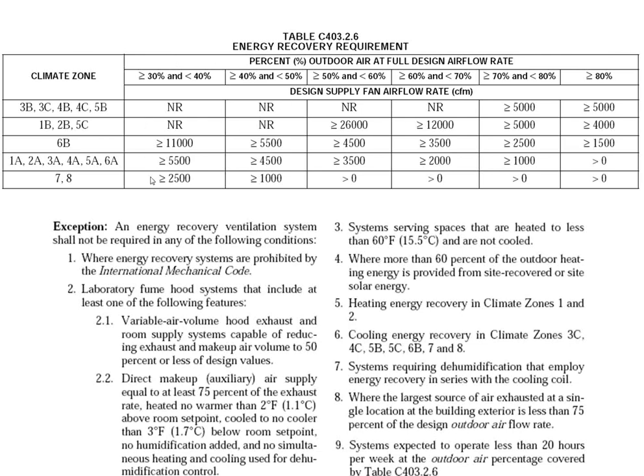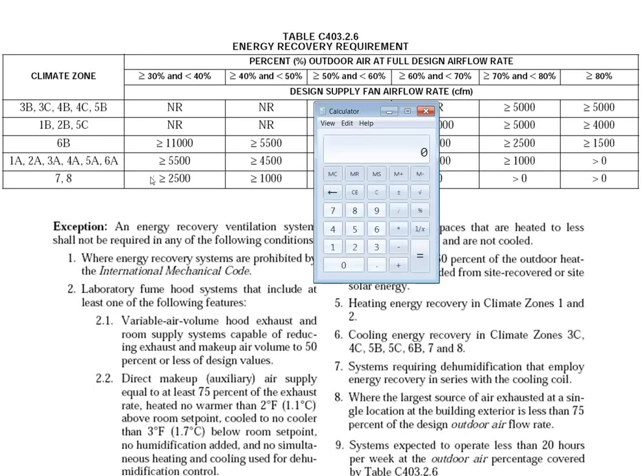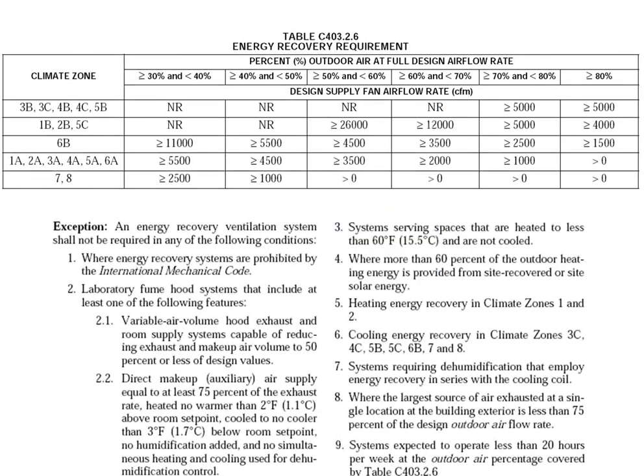If I got a system that's 5,500 CFM of supply air, right? What's 5,500? Nominally speaking, 13-ton system, right? 13-ton system and larger with 30% outside air, I have to put an ERV on by code. 30% air happens a lot more than 70% air. Yeah, it won't be every space, but it'll start including things like schools, daycares, and those types of facilities. All right.